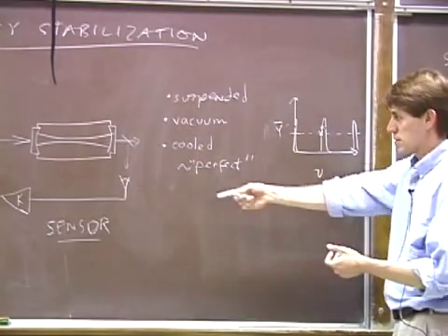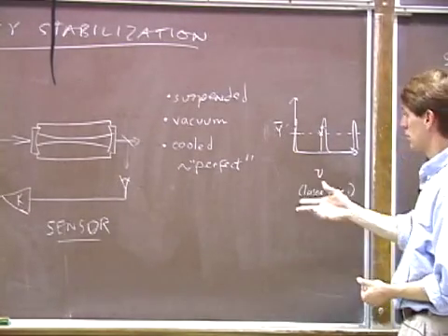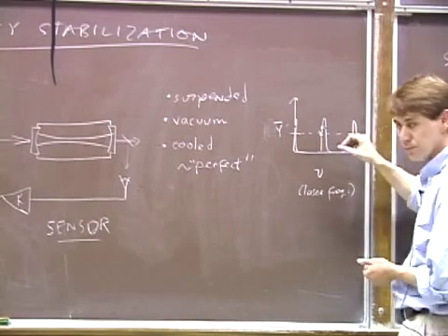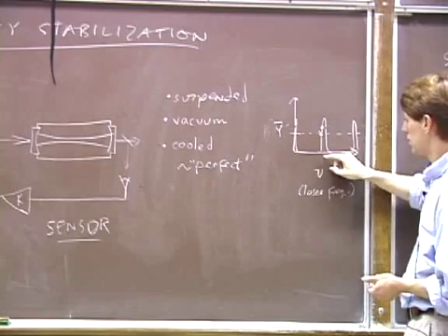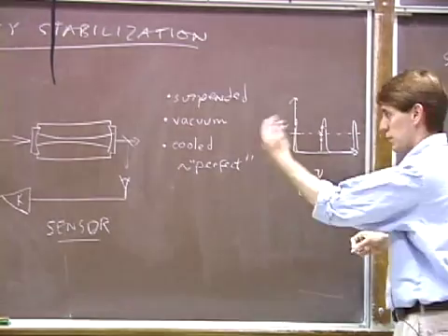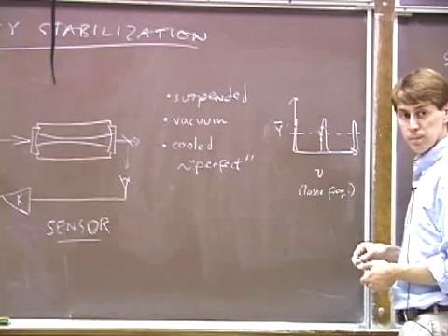The system, okay, it's got a minus sign built into it. It would reduce the laser frequency, push it back down, and bring the system back to its set point. Similarly, if the laser frequency got too small, the power would drop, and the servo would give it a kick and push it back up to its set point.